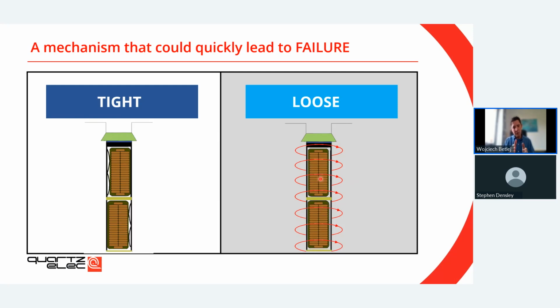The difference is when you have a loose coil in the slot, things can move. Obviously, you have magnetic components moving around. You have electromagnetic force moving these coils side to side. So if your stator slot is loose, you might end up with this problem. And on the left-hand side, you have a nice ripple spring on the side, preventing that slot content from any movement. So have that in mind.